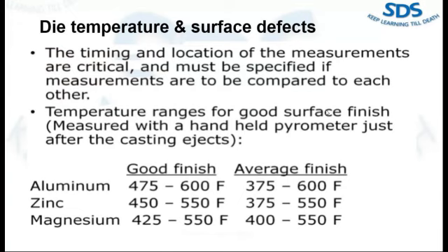As you increase your die temperature, as I told you, you reduce the percentage of solid, so you will get a good finish. As you reduce your die temperature, the surface finish will be average.